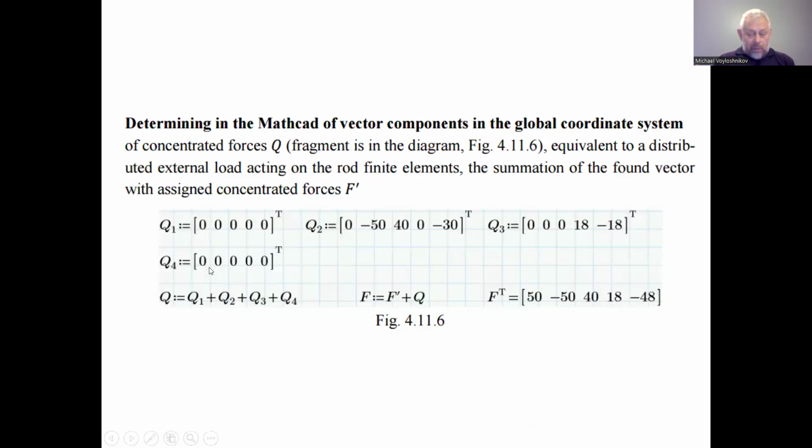We have 0, 0 of the 5-component vector of the forces acting in the nodes whose displacements are subject to find. We have 5 displacements to find. For the node 2, we have 3 displacements, 2 translational, horizontal and vertical, and 1 rotational of the node of the rigid corner 2. And we have only 2 displacements to find for the node 3, because this is a hinge without bending, we consider only the translational displacements, horizontal and vertical. So together we have to consider 5 displacements.